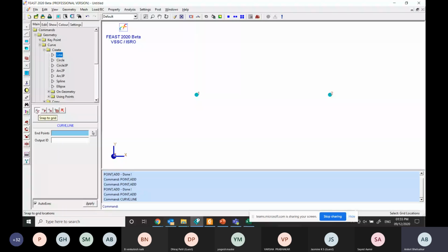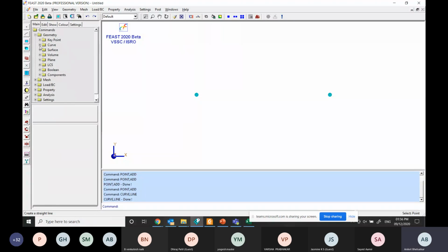You can see we have the C filter, P filter, N, which stands for point filter, node filter, and snap to corner, where it will take the vertices also. So I'll use point filter. I'll choose first point and the second point. So 2 points are selected. I'll just repeat the process. Okay. Once these 2 points are generated, I'll go to geometry, curve, create, line.